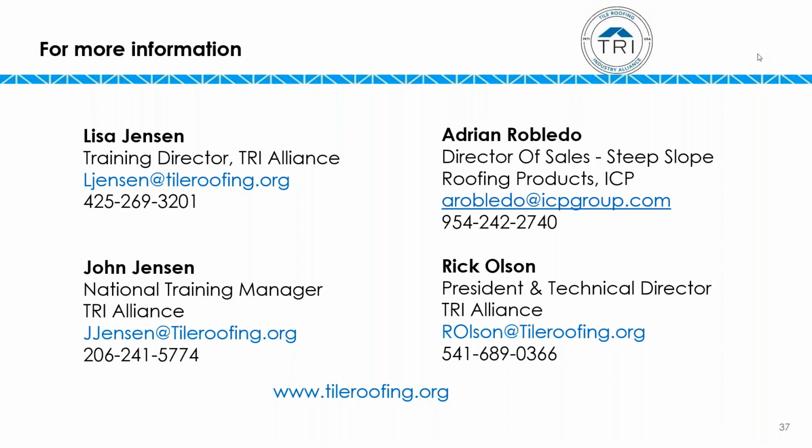Thank you so much. Appreciate that, Adrian. No problem, Victor. And real quick, Sue, back to your question. You don't have to break the tile if you can somehow shimmy it out. But what we found is sometimes when it's screwed or nailed, that's where it's very difficult not to damage that tile, where you will have to break it and put a new piece. Yeah, we found that generally if it was nailed or screwed, there's a bunch of methods to get that nail or screw out. But when it's foamed in, it tends to want to be broken.